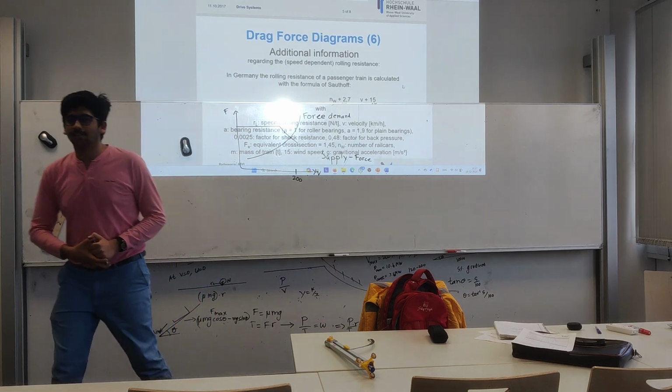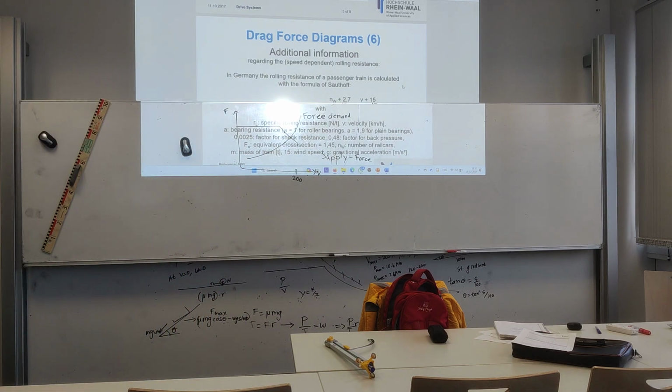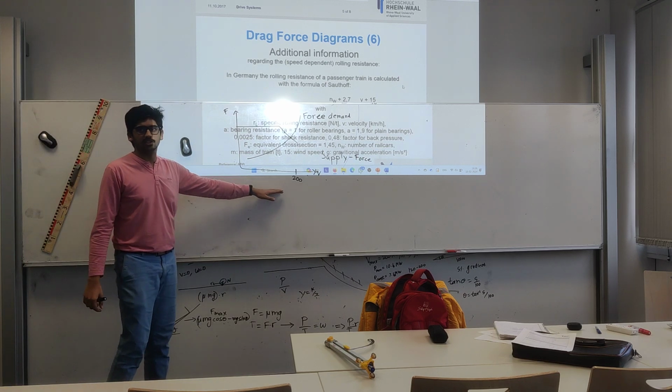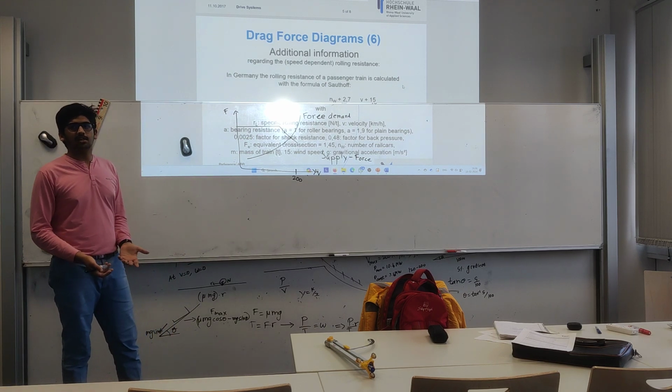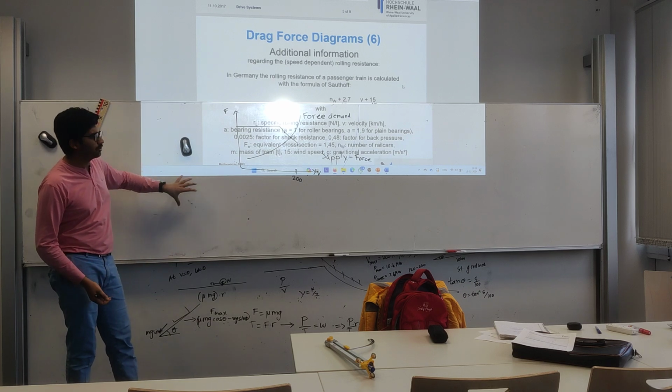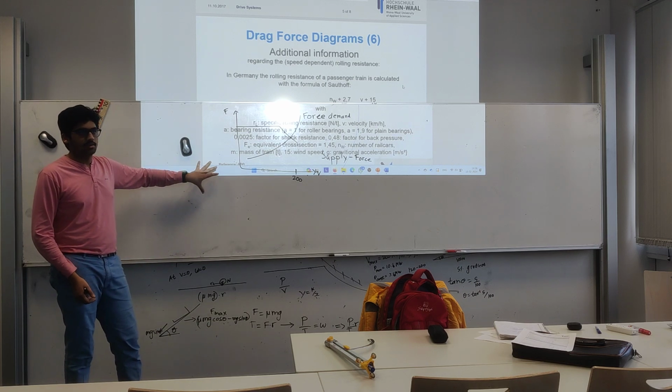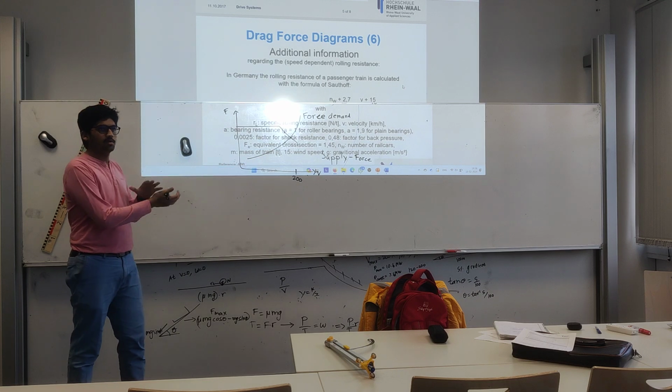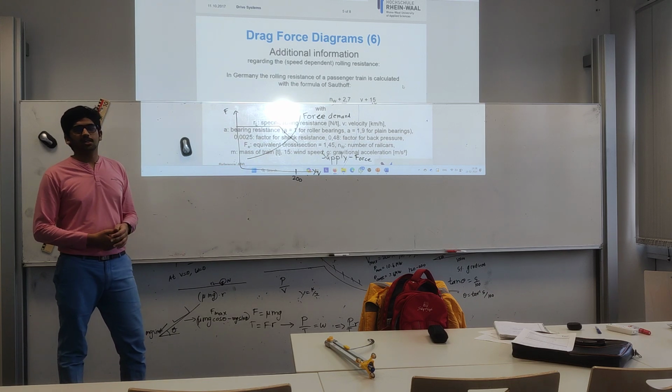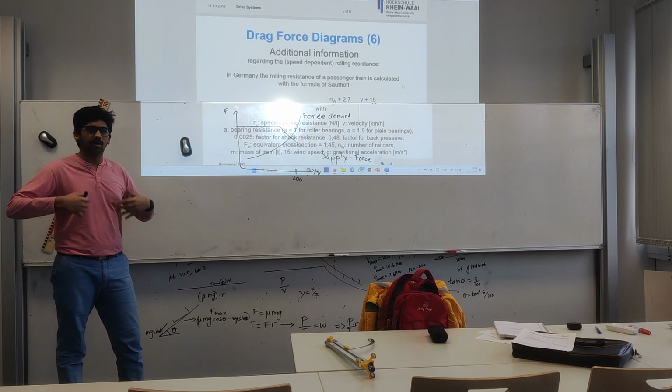That's why passenger trains don't go for locomotives, which are a separate engine with cars behind them, but have motors below each of the cars. Each of the cars has a normal reaction, and you don't need to increase their mass because you're using that normal reaction only for that part of the car, and the next normal reaction is for the next part. So you have a much higher top speed, and you don't need to additionally increase mass.